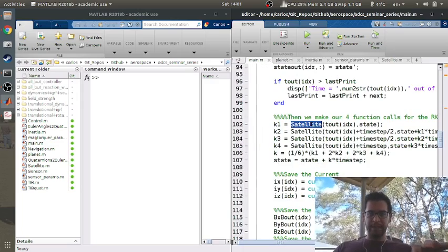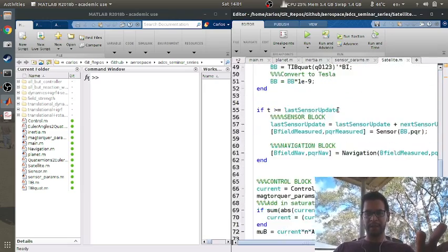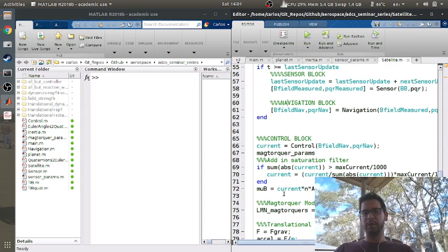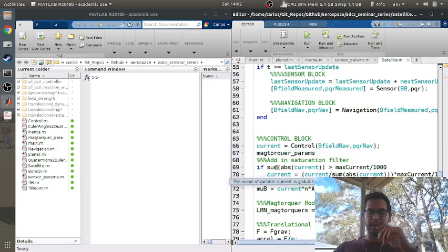We have the satellite dynamics routine. That is in here. I haven't really touched this much. I just looked at it again to make sure I understood that this is where we measure the sensors. This is where we perform our filtering. We compute our control law every time. So this control law is going to need to get edited to compute the reaction wheel speeds.